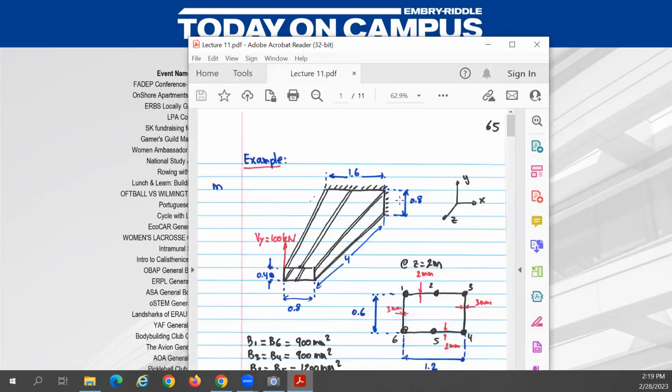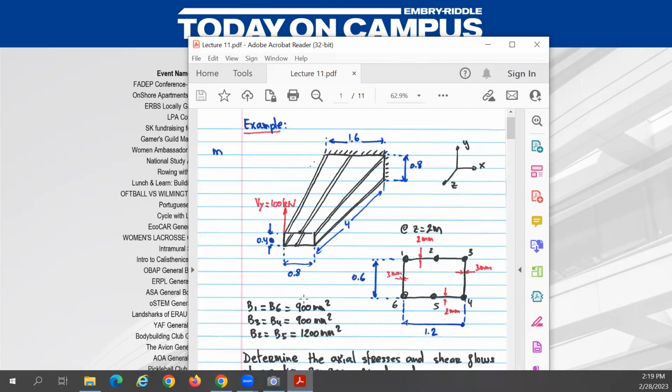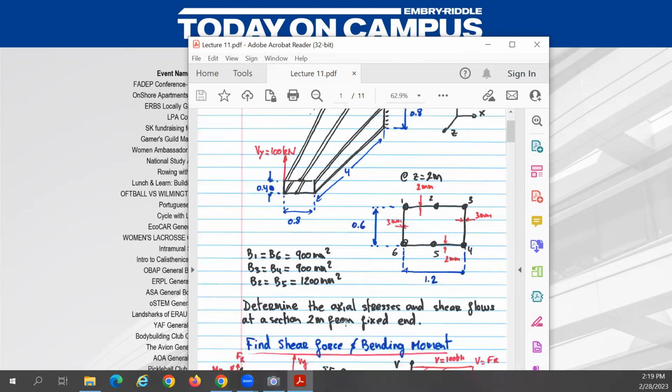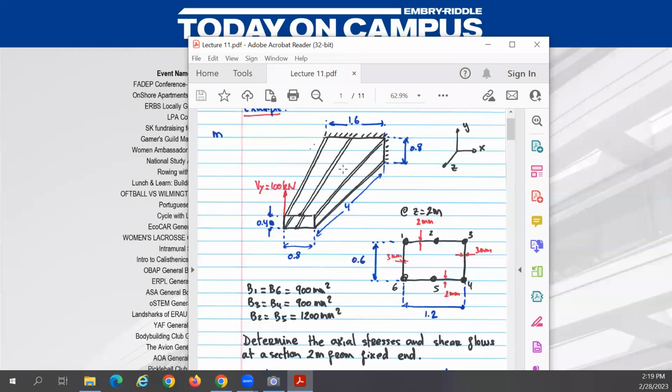Last time we started this problem, basically here we're doing the wing spars, which are tapered. So basically tapered means what? That you see the width over here is not the same as the tip, and the height is about the same thing over here. So the process is the same thing. In this problem, I think we needed to calculate that at 2 meters from the end section. So right in the middle, we make a cut. So in the middle, we have what? It will be, because it's linear, the height, instead of being 0.8, will be what? 0.6, no? Same thing for the width.